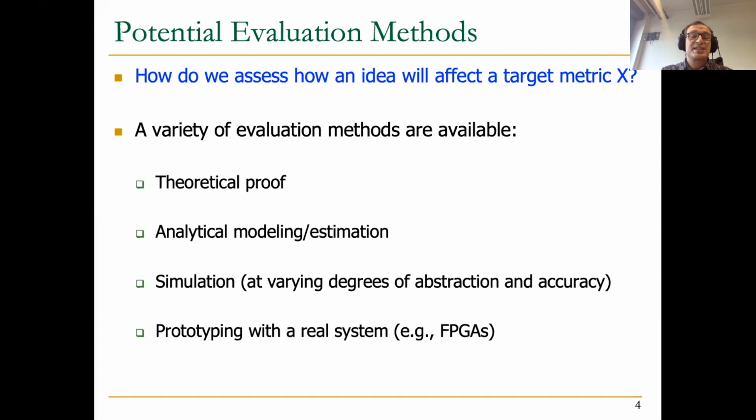If you're prototyping, for example, a general purpose CPU on an FPGA, you would be limited by the clock frequency and the connections that you have and the space that you have on the FPGA. So you may not get a fully accurate picture of what kind of performance you would get when you actually implement your idea in the real system. But you may get closer potentially, and you may actually have to solve some problems that you may not otherwise have to solve in simulation, and certainly not in analytical modeling, because you're actually really implementing your idea in a prototype system. But keep in mind that this real system is always different.